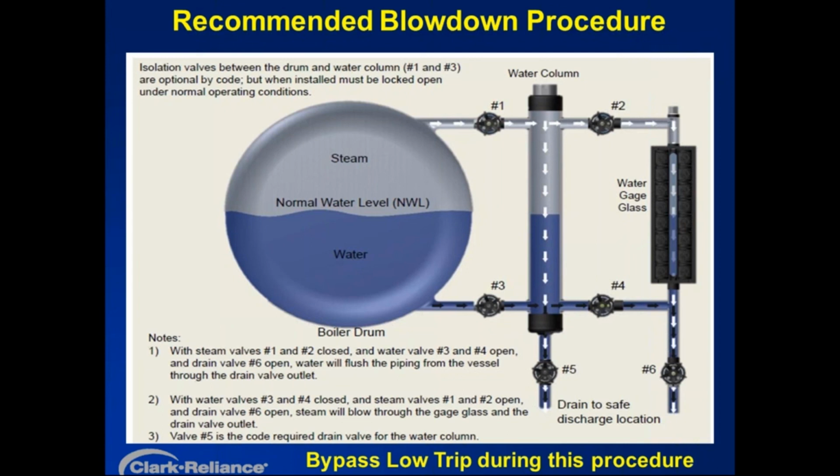Then close those or leave them open and then open the steam valves and then return everything to normal. But the idea, the concept here is to isolate the steam valves, blow the water lines down, then you could isolate the water, blow the steam down, and then return everything to normal. The reason for blowing water first, steam second, is to clear any debris, and then with the steam, flush any debris out the drain.